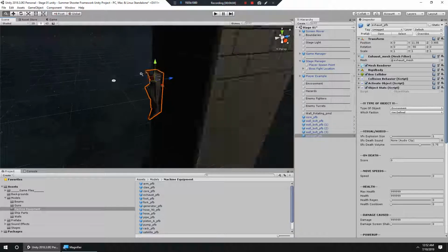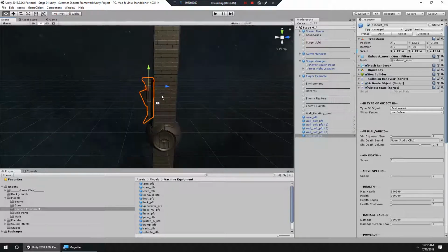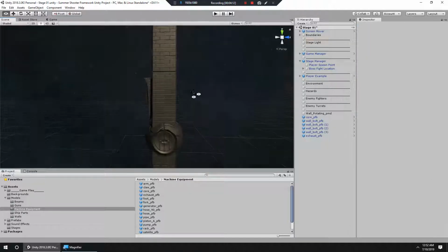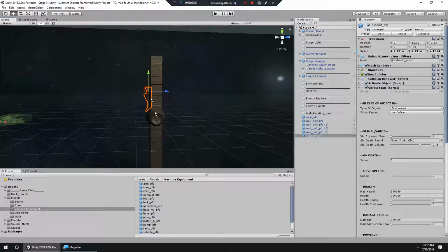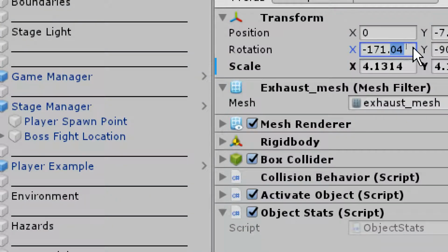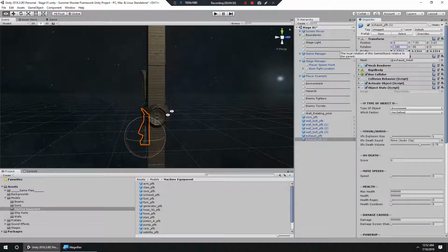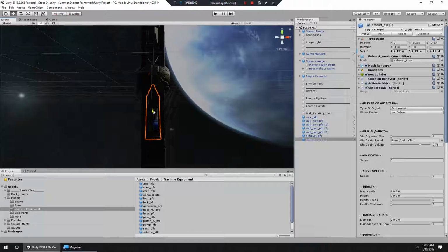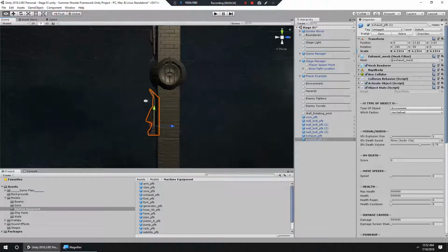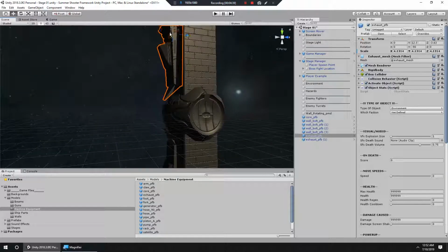And then I'm just going to scale it to how big I want it to be. So, you know, just put some nice vents on the side of it, like so. Give it some, make it look pretty cool. And I'm going to bring it down here, and I'm going to rotate it 180 degrees in the X. So you can see I'm not quite at 180 degrees. So I'll do one negative 180 to make sure we're completely up and down. And then I'm just going to position it kind of like how I got that one positioned. Ooh, maybe put that little ridge point up here.